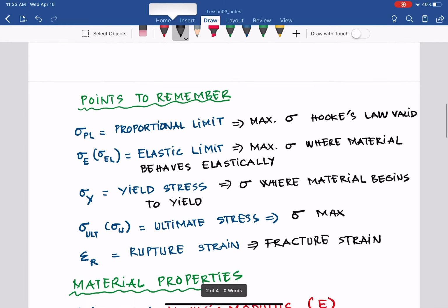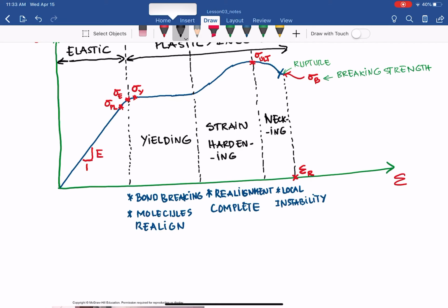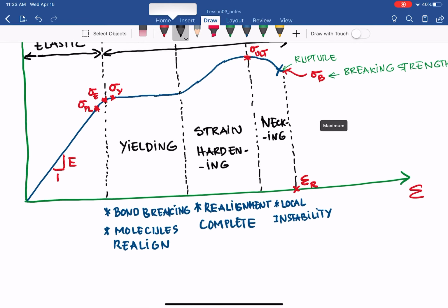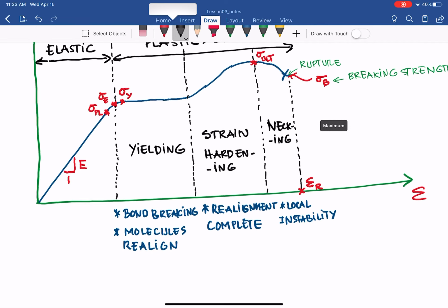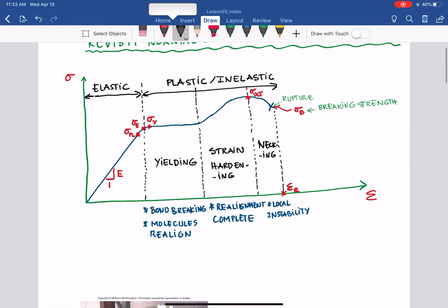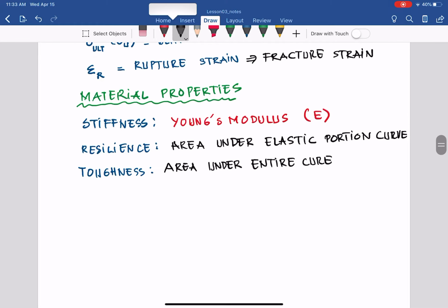So that is the area for the whole thing, going from the proportional limit up here. See that? And the entire curve in there. So the area between the blue curve and the green horizontal line is the area that measures the toughness of the material. To measure the strength of the material.